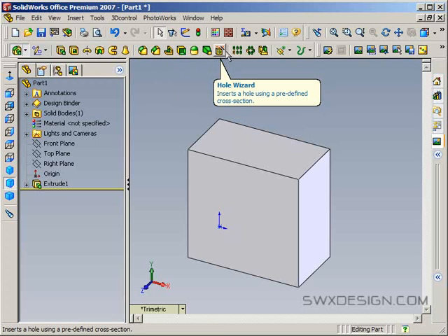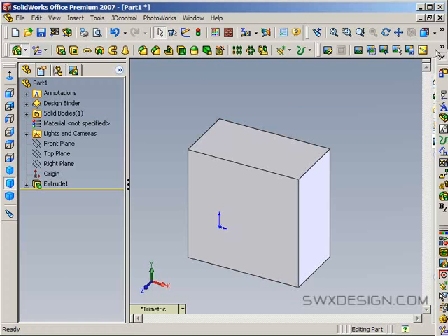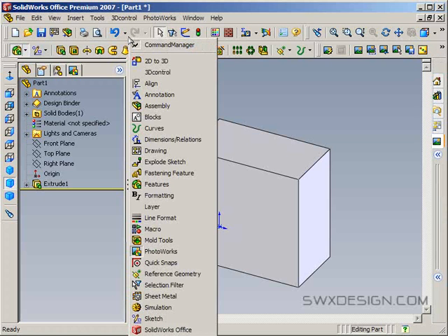The way you select and deselect toolbars is to go to any blank space in your toolbar, like over here, that's not going to show up. Up here. Unfortunately, I can't show this entire menu in the screencast because I'm working at 800 by 600, which is probably significantly smaller than what you've got on your own screen. So everything's going to appear like it's not fitting very well on mine. If you right-click on these toolbars up here, you can select which ones are active and not active. So you definitely want Command Manager to be checked.